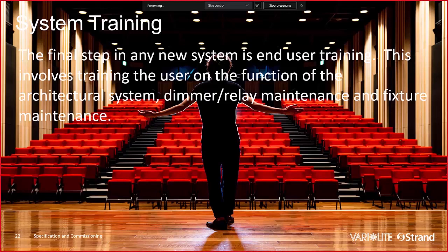So it's generally going through and identifying how the fixtures function, that they have a little screen on the back where you can see DMX addresses so that if fixtures are ever moved, one understands that they're still going to communicate over that same address unless you choose to alter that. If that gets changed, then it has to be changed both on the commissioning file from VisionNet and on the console file. So it's not something to be done lightly.